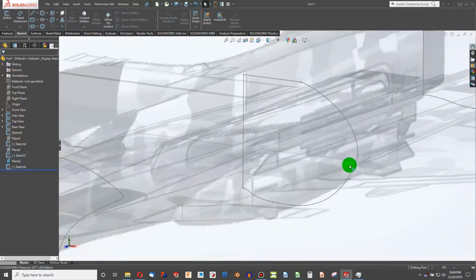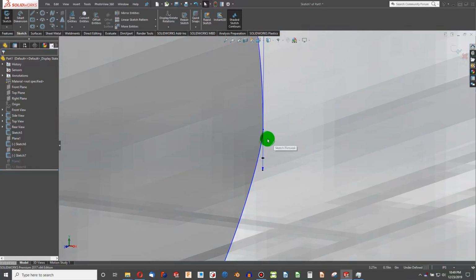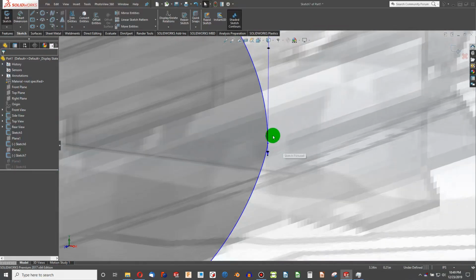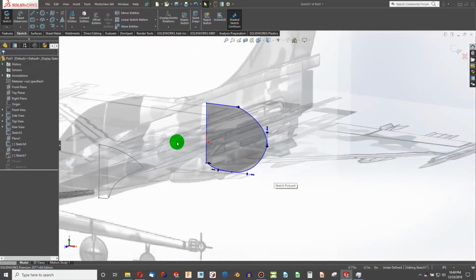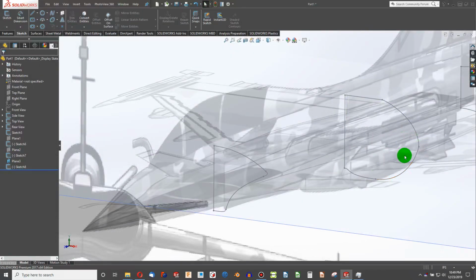Next thing I want to do is make a little reference sketch. And I also, yep, so they are tangent because we're vertical. So just making sure, that didn't look vertical because I've got a really tight curve right there. So that, for example, could be an issue when you go to thicken it if you were to do this in surfaces.